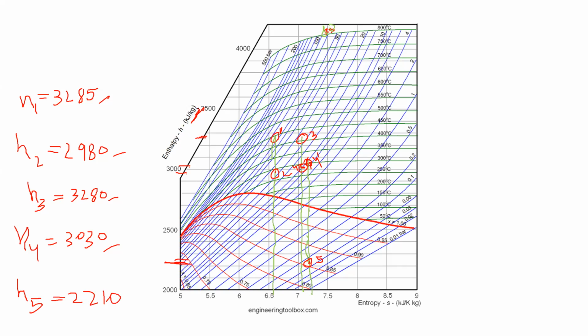Usually the kilojoules per kg is the enthalpy. If you look at this Mollier chart, I am taking the enthalpy at the first state, where we have 450 degrees centigrade as well as the 70 bar line. Those two lines meet at this position. I'm marking just this position. At this condition, I have the enthalpy of this much, that is equal to 3285.